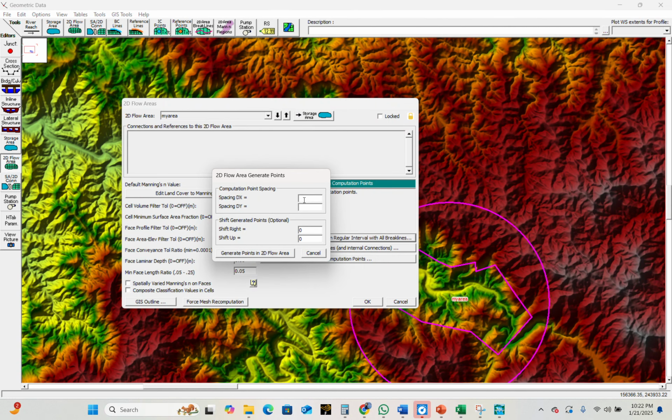I have to mention this point: when you provide a mesh, you have to be aware that we have to change the dimension of the model and reduce the size of the mesh until we don't have any changes in our result. We call it grid dependency. It means that